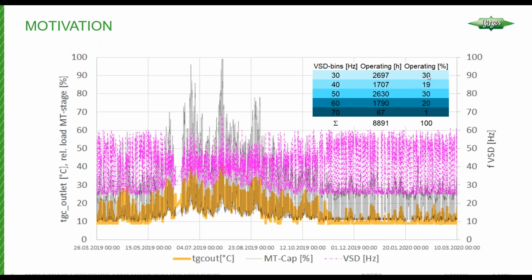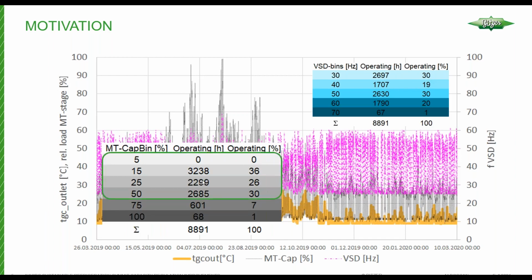And that is a direct result of this next section here that shows that about 90% of the time, the capacity requirement in column 1 here is 50% or less of the actual design condition. So based on this information, this example, about 1% of the time, this system is running at its design condition, which is shown up here at the top of this graph right here. So this makes proper suction pressure control or temperature control and part load operation essential for a smooth running, efficient system.